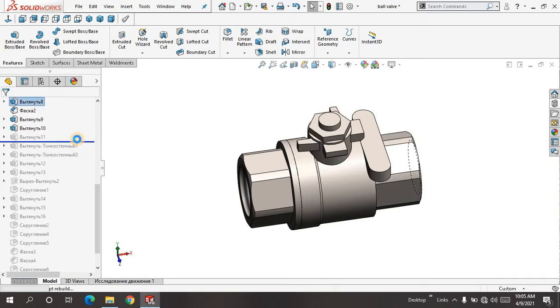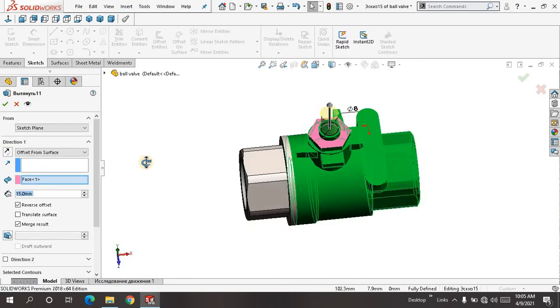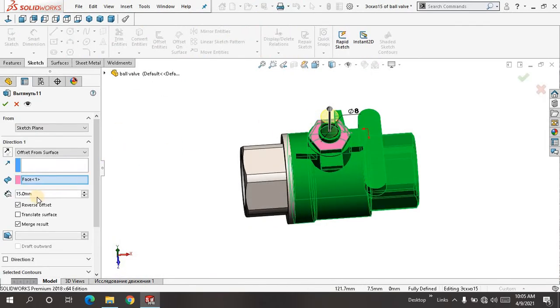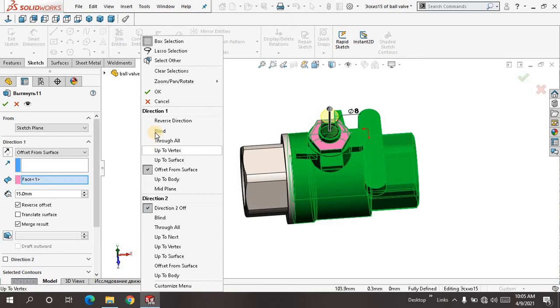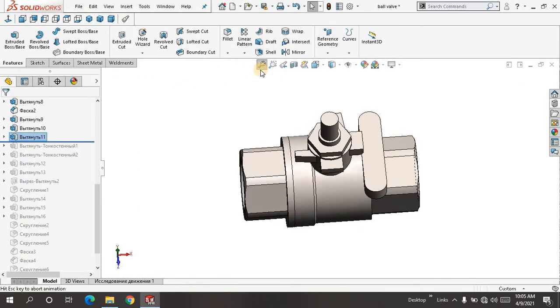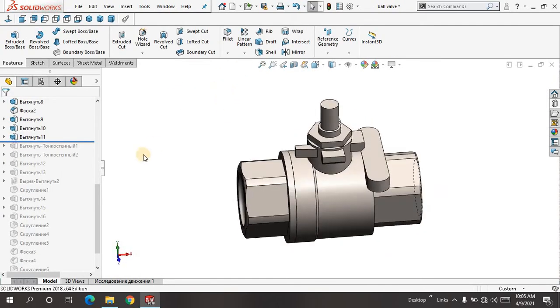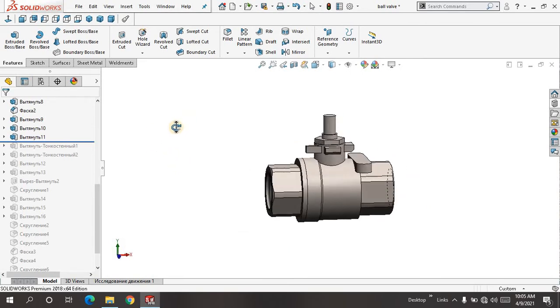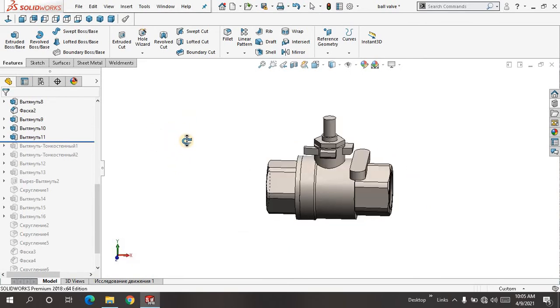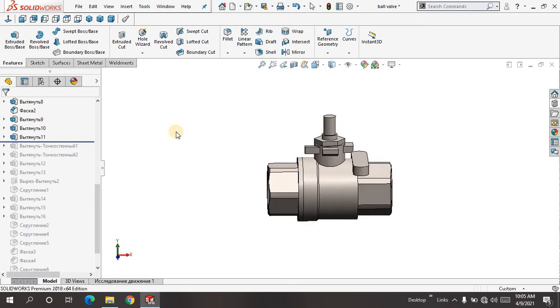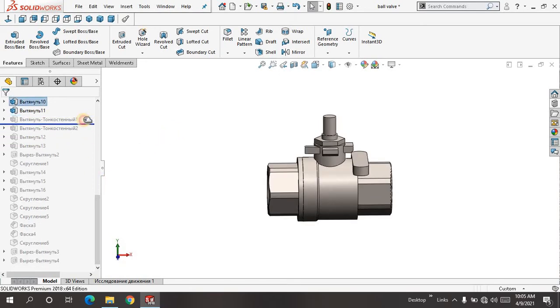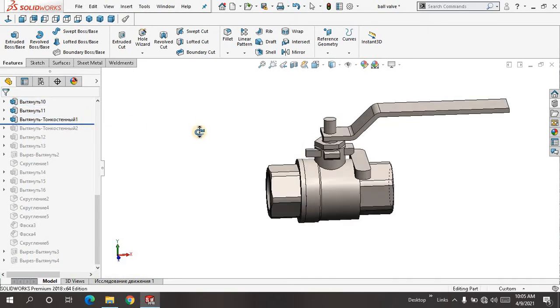Again, when I come downward, I add another extrusion, having diameter of 8 mm and extrusion of 15 mm. Merge result you have to check. I will say OK. Now next, you can see your wall is going to build up. This is not really very difficult for people when you follow. Okay. When I come downward, I added this extrusion.